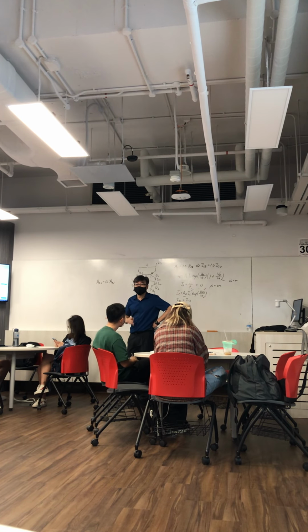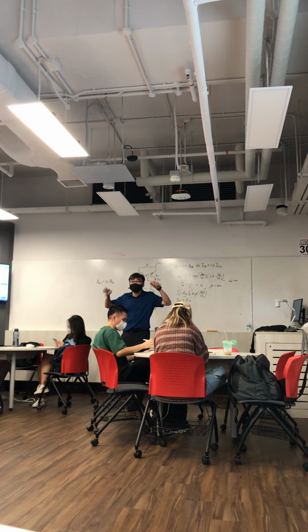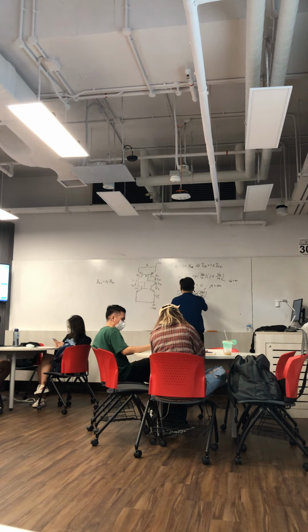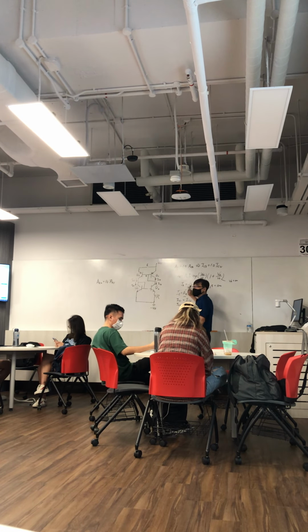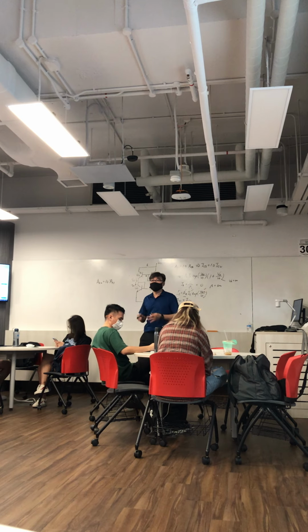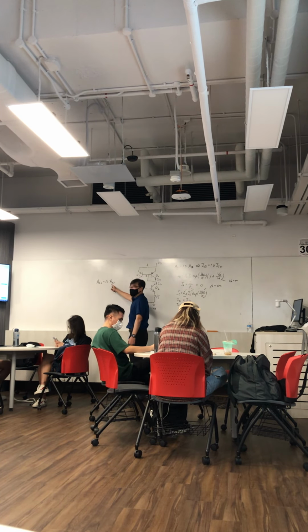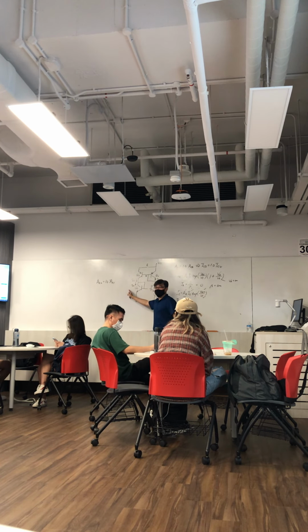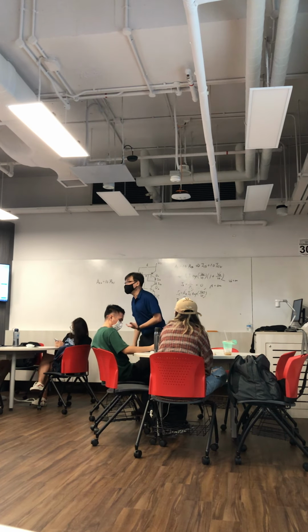So the VBE is not the same. How can the IC be the same? Look at this equation: although these are the same, the VBE is different, which means these two will have to be different. So there's no contradiction. It's just that I cannot say that because of this, this is 10 times this. Only when the VBE is the same.